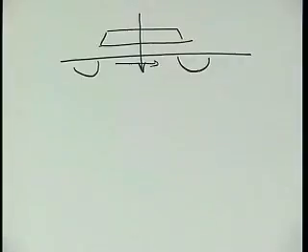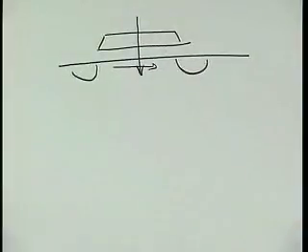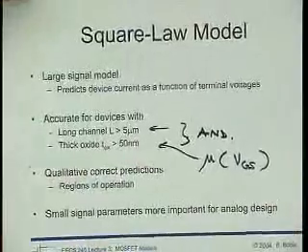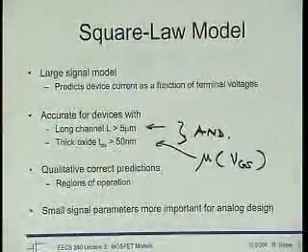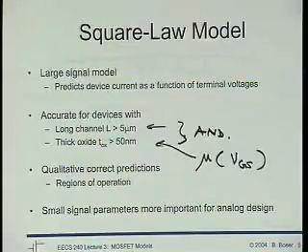And the key thing is that the electrons slow down, and so suddenly the current and mobility and so on depend on VGS. Well, that's not in the square law model, which assumes that mobility is a constant, and consequently you get the wrong results. Right? Okay, so totally regardless of channel length, for modern devices, a simple square law model will not give accurate results, usually.